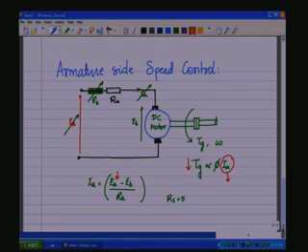All this while phi is kept constant, and because the generated torque has decreased, for the same load omega, the rotational speed, also reduces, and this is going to affect EB. EB is going to reduce because EB is proportional to omega. So, it will settle at the new equilibrium point or the new operating point. This is the sequence of parameters that get affected if you reduce EA.